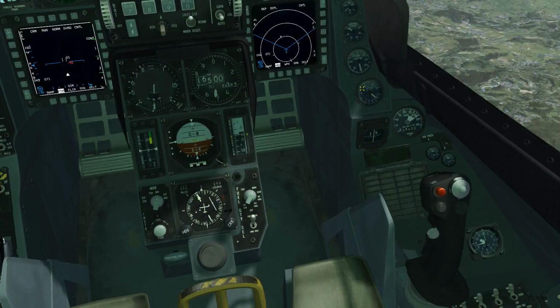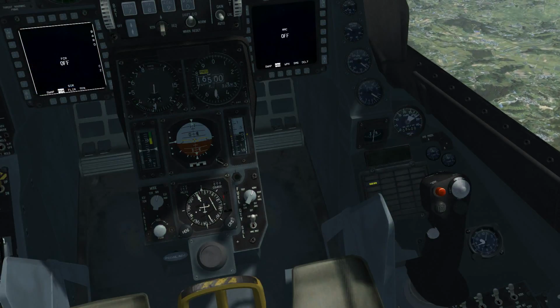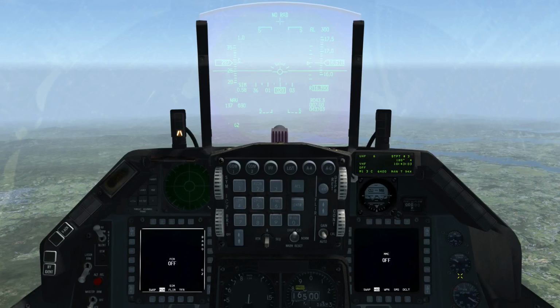There we go. So the normal flight idle is 70%. So if I let the sim run a little bit further, then I see that the idle is going down below 70%. And hey, the lights went out. I had the cockpit floodlights up, so that's an indication if you have those on. I also see that the nozzle went to the full open position, up to 100%. So that's kind of telling me that I got something funny going on with the engine.